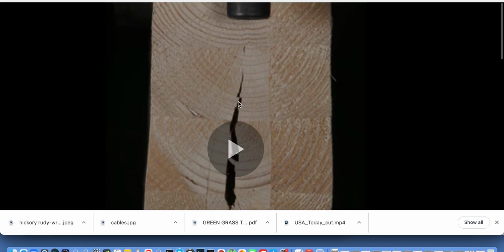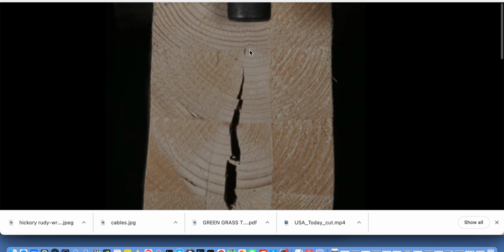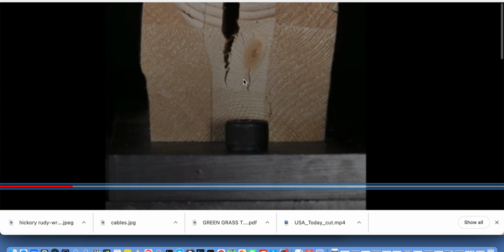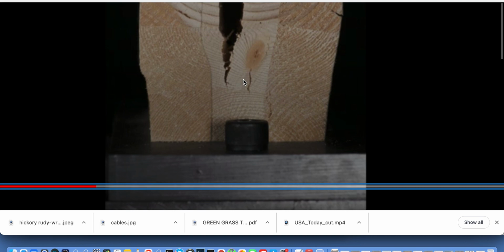There it goes. Alright, so it's already made it there. That's just another compressive moment. Let's see, coming down here. Large blocks of wood separated. There we go. So you see the last blocks of wood separated. It's following the stirrup line, as you see. And there's the stirrups breaking apart and shearing apart, and there's the rotation of it.